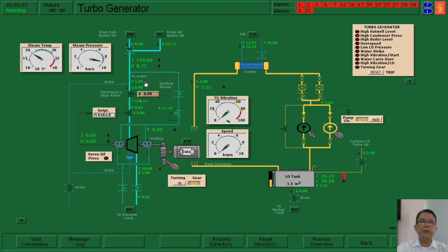So we have to do it slowly. Before starting this valve, we find that our density concentration is already high. So let us drain first, and once it is empty, close it, and then start with our emergency stop valve, or what we call the trip valve.